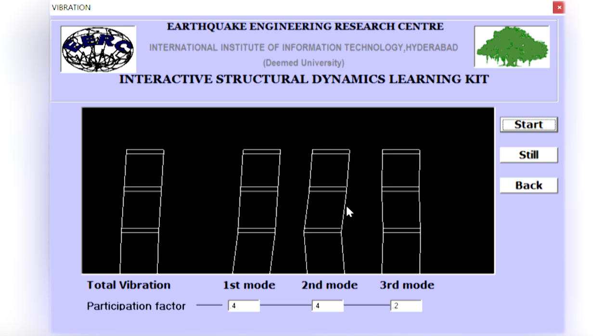When we look at a multi-degree of freedom system, say n degrees, some 10-story building, 20-story building, it will have a large number of mode shapes. So how many mode shapes do we need to consider in doing time history analysis of, say, a 20 degree of freedom system, a 20-floor building? A usual suggestion is that where mass participation is more than 95%, that many modes you consider. So mass participation more than 90% means what? First mode is participating, giving say 60%, second mode giving say 20%, third mode giving say 8%, fourth mode giving say 2%, 3%, something like that.